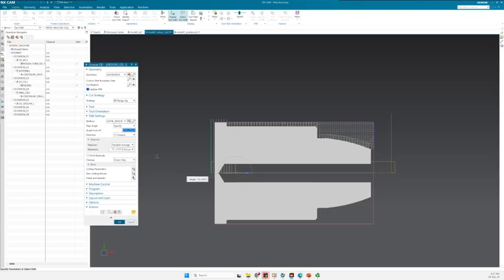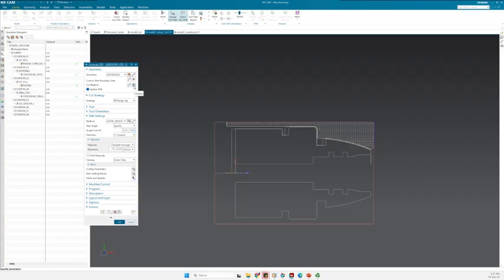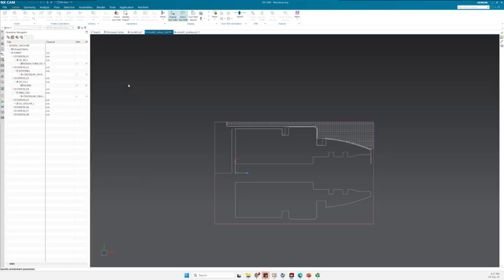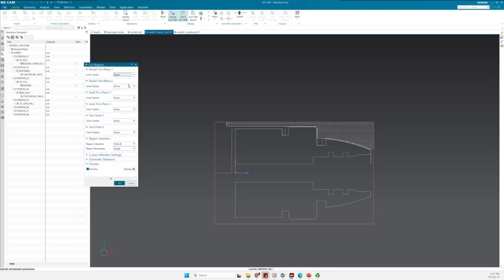So how to solve the problem? It's actually, again, easy. What we need to do is to check the cutting region. You can see that now this is the cutting region, and actually at the end it kind of does the cut off of the parts and then goes here. So this is not what I want. So I just go to edit, and I need to define two axial trim planes, on either side, both sides of the groove.